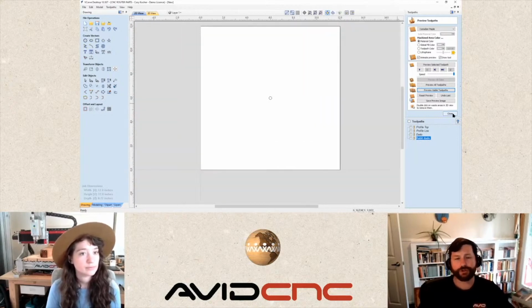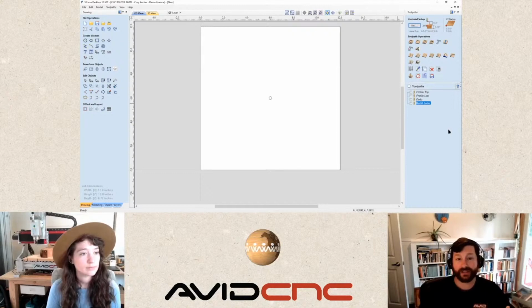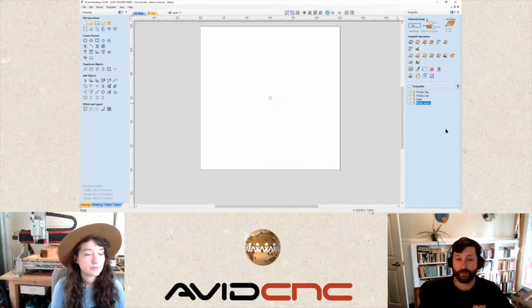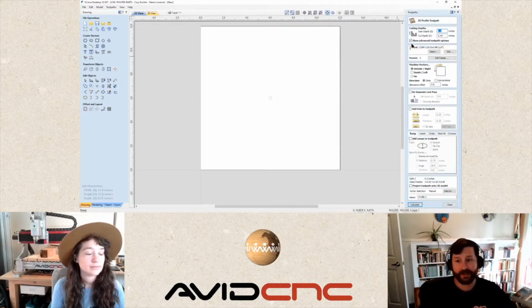Now, you could use a router bit that's specific for drilling holes at that diameter, and those are great if you have those. I know these are used a lot for pinholes, for shelving, and different things. If you have those specialty bits, they're going to work great here. But if you don't, let's talk about how you can create the best scenario for drilling down almost 3x your hole diameter in depth, and I think this is with a profile pass on the inside.